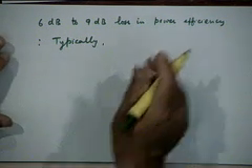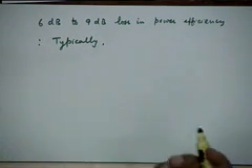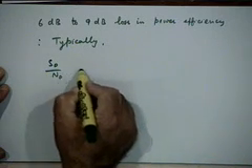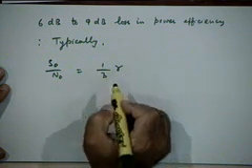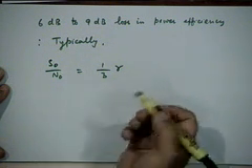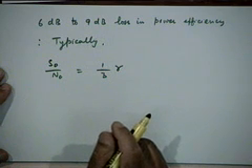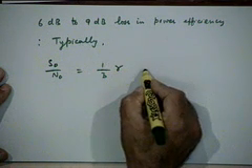3 dB is the absolute minimum value. For example, suppose your modulating message signal m(t) was a sinusoid, just for the sake of discussion. What is the peak to RMS value for that? Root 2. Peak to RMS is root 2. So, what is mp square by m square bar? It is 2, so instead of 1 it is 2. So, what will be the value of S by N naught now? It will be gamma by 3, which is about 4.77 dB less.